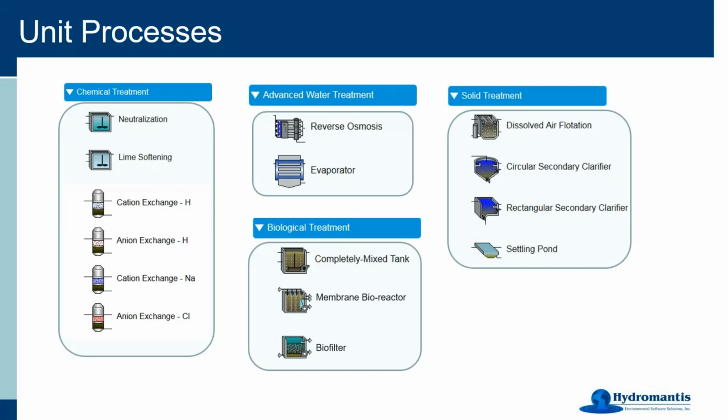On the solid treatment side, we are, of course, not only concentrating on the liquid side, but we are also managing the solids that are being produced, and we can look at how you manage your solids in the system. So there is dissolved air flotation for thickening the solids. There are some settling ponds, and there are some dewatering and thickening unit processes that can be utilized for handling your solids.